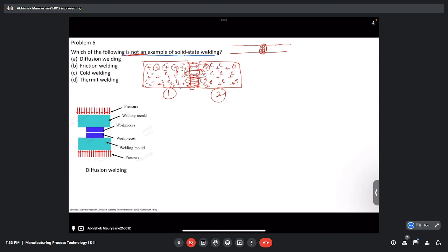This kind of process will take place under some conditions. First, the contacting phase or the faying surfaces should come very close. Another thing is, for the accelerated movement of atoms and electrons from one body to another body, we have to increase the temperature.